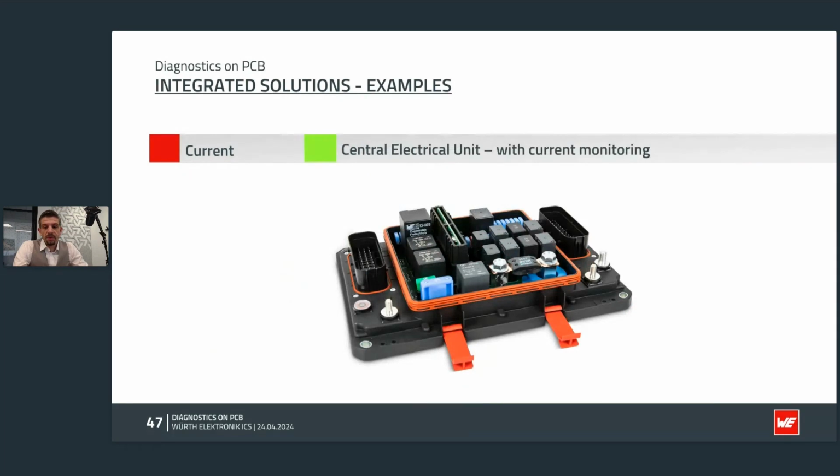And here you have an example of our demo box for the CDM A16 module, which stands for Control and Diagnostic Module, especially tuned to read the fuse status, supply and acquire some sensors on the main board, and control the relay with pick and hold function to reduce its heat generation. On this board, we will offer 3 different current sensors. The most obvious is a huge LEM sensor, which is directly connected to the main fuse on the box, 2 different ways to read temperature, and many other diagnostic possibilities, along with an effective 150 ampere power distribution capability.